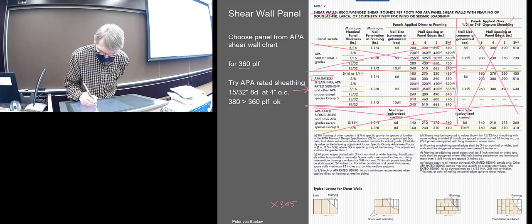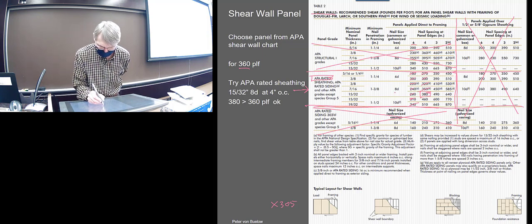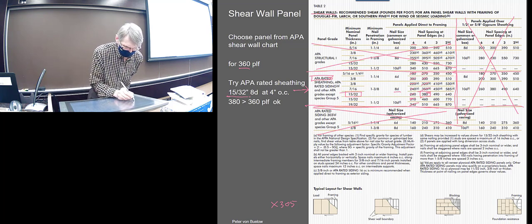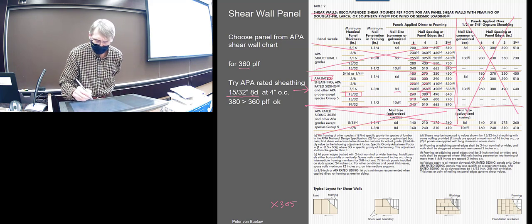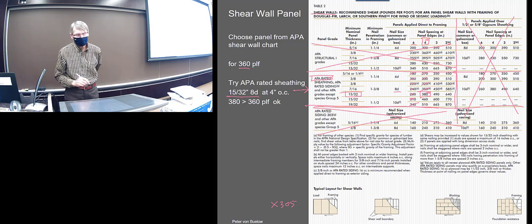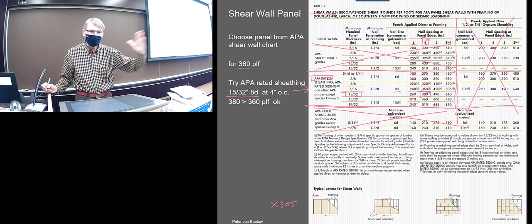No, almost that one. So that looks like, my friend, 8 penny, 15-30 seconds. So is that what I got? 15-30 seconds, 8 penny, and 4-inch nail spacing. So that picks that one out of the chart. And like I said, normally that's the way you do it.